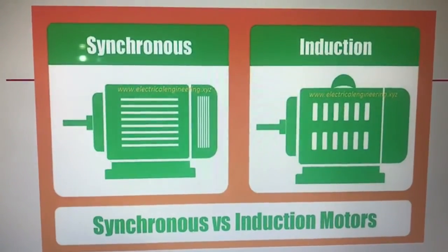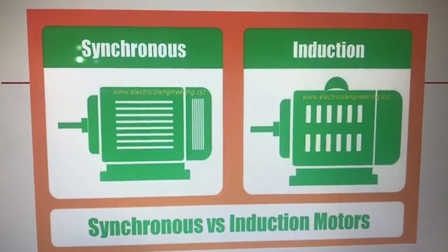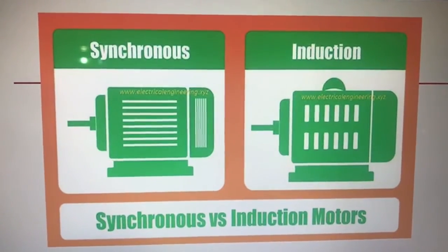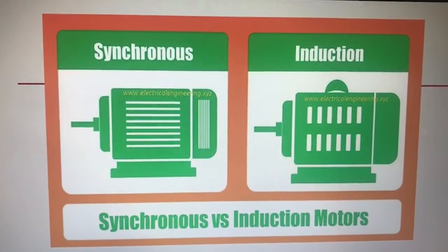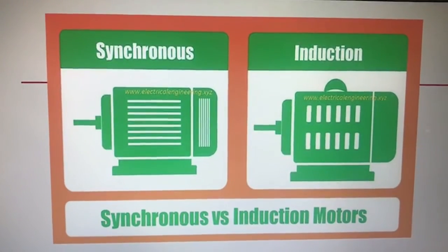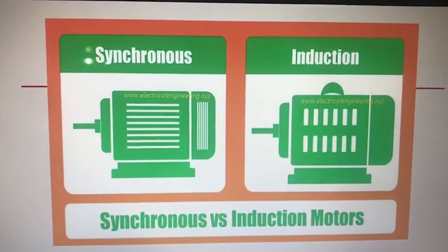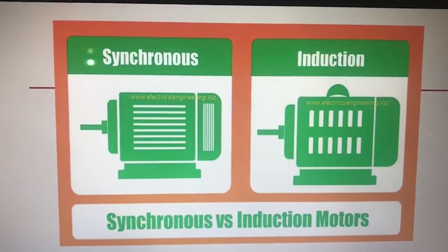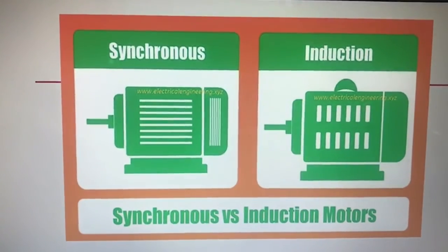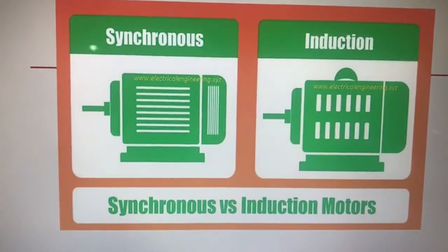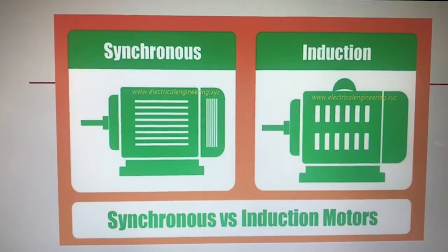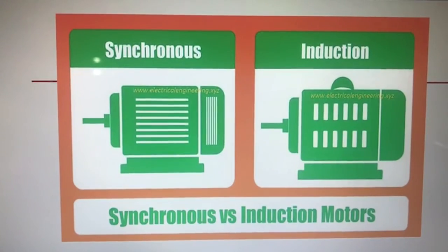From the above, we have concluded that a synchronous motor starts on the induction principle. The damper winding acts like the squirrel cage rotor, producing the starting torque. In the starting operation, the field is kept shorted while the stator is switched on to the three-phase AC supply. As the motor speed gets close to synchronous speed, the field is energized from the DC supply. The rotor then gets synchronized automatically because of the coupling of the rotor with the stator magnetic field. A high starting torque synchronous motor is a combination of synchronous and slip ring induction motor in one machine.